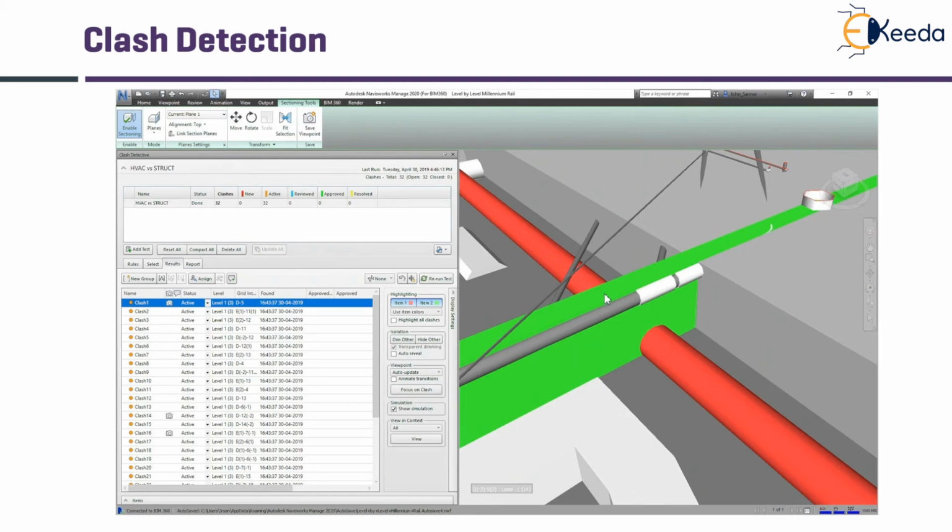The first item is shown in red, the second item is shown in green. That is, here we can see that a pipe is probably crossing wrongfully through a structural beam. Therefore, as an immediate action, the pipe level can be lowered down or it can be bypassed through some other route.